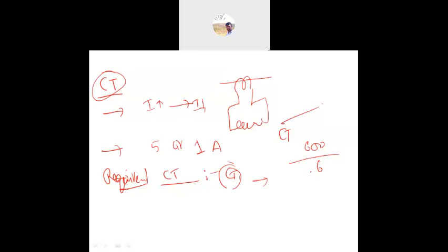This is due to the fact that the relay has to perform reliably at normal current. If a fault occurs, the relay will operate, so the CT has to measure values above the rated value as well. It should measure the above rated current, and the secondary side should also reflect it. So it must work at normal current as well as fault current.